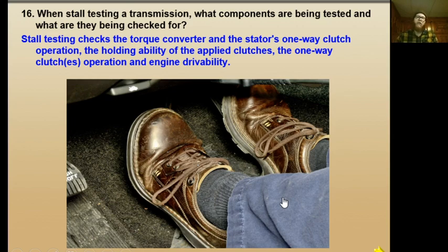If the vehicle is four-wheel drive, I often like to put it into the four-wheel drive mode because the back brakes, especially on pickup trucks, aren't really expected to do a whole lot because most people drive a pickup truck around like it's a sedan, so empty in the back, so all the weight's up front. So four-wheel drive will make it so your torque is evenly split between all four of your wheels, and you're less likely to do a little brake stand in the shop.